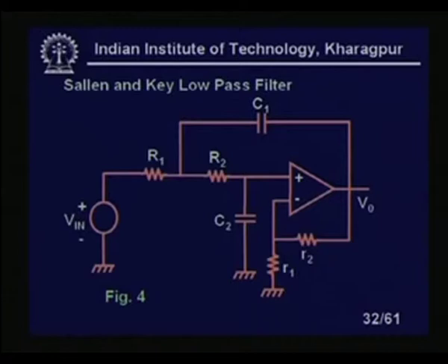So, this is the famous Sallen-Key low pass filter, which uses a single amplifier structure where we need 4 resistors. These 2 resistor values are different, this small r1 r2, and they determine the negative feedback which you are giving in a positive feedback circuit. This is your RC network, so it is a positive feedback topology because the RC network is in the positive feedback path.